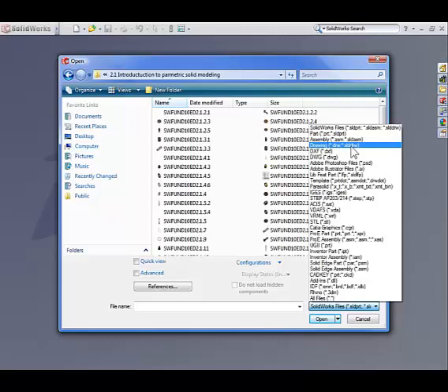The bulk of the list contains file types for many of the more dominant CAD standards, including DXF, Parasolid, and STEP, and some native file formats such as Inventor and Solid Edge parts. At this time, we're not going to go into importing file types other than SolidWorks files, but it would be a good idea for you to familiarize yourself with some of the other file types that SolidWorks can open. Instead, we only want to see assemblies, so we're going to click SolidWorks Assemblies on the list.